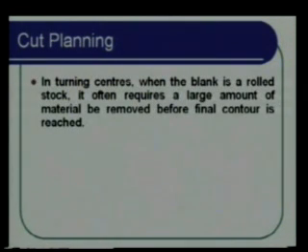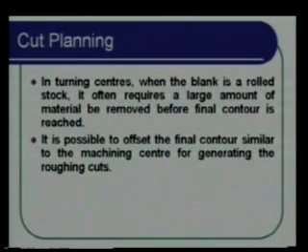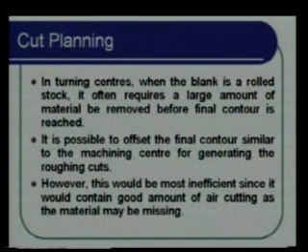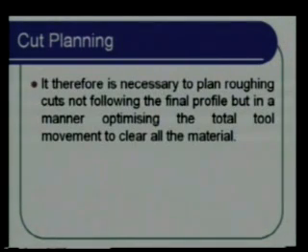Okay, the main thing to remember in turning center programming is cut planning. What happens is, because we will be starting with a raw stock, which is generally bar stock, we will be removing a large amount of material before the final contour is achieved. So we will have to identify how many cuts are to be given and how and where. To do that, it is necessary to plan all the roughing cuts and then identify the coordinates through which the tool will have to move in order to achieve those cuts.